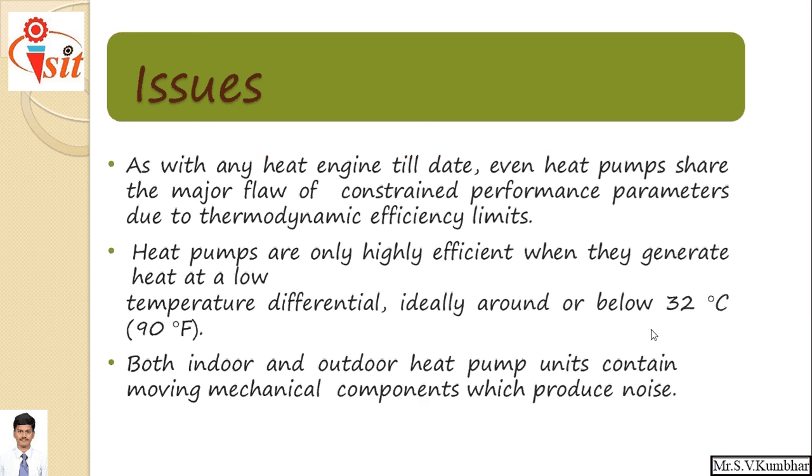Second, heat pumps are only highly efficient when they generate heat at a low temperature differential, ideally below around 32 degrees centigrade. Third issue, both indoor and outdoor heat pump units contain moving mechanical components which produce noise. Noise is the biggest disadvantage, which can be taken up as research work in the case of heat pumps.